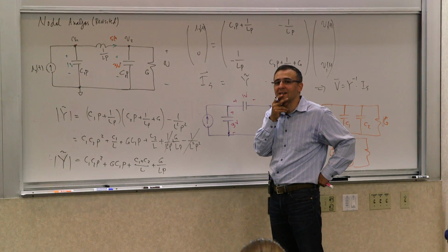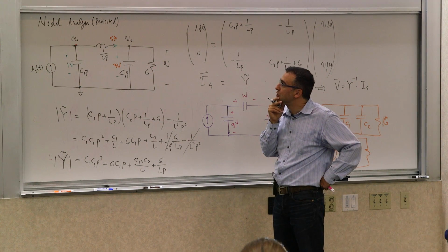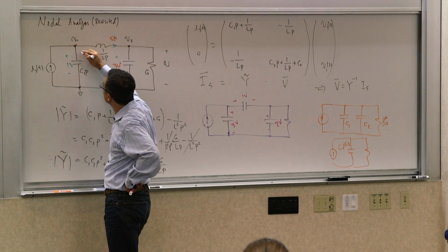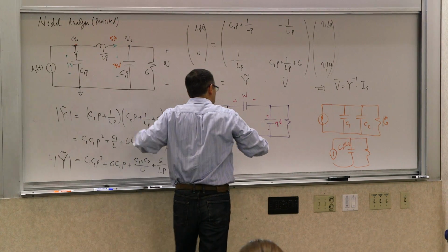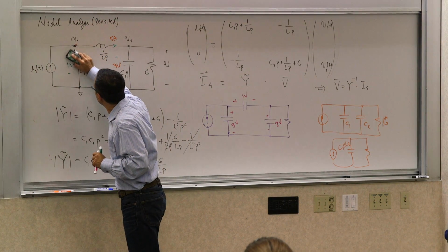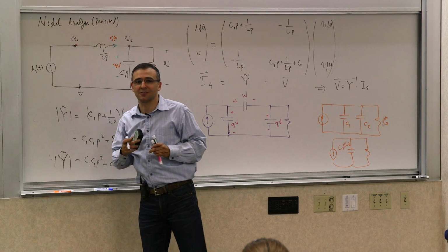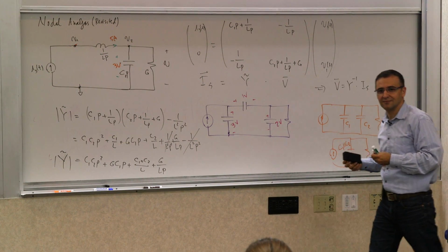Is it clear why? Isn't the current somewhat dependent on what IS of t is? Sure, but it's not fixed by it because there's also this third current. You asked another good question. Here, if I take this out, now what's the order of the system with the current source? 1, exactly. Why?